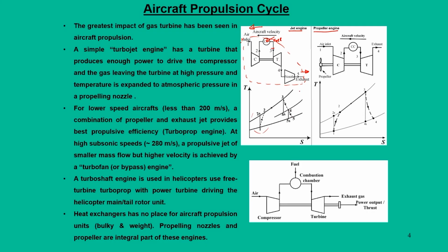But the only difference is that now turbine expansion gives you power, and expansion in the nozzle gives you thrust. This is one concept. The propeller engine concept is also similar. Here we do not have a nozzle, but rather the exhaust goes out, and through that exhaust we get some thrust. Side by side we have a propeller, which is driven by these turbines.